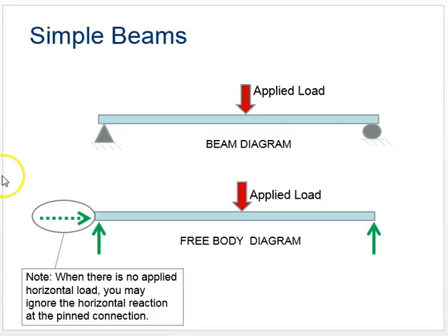This is going to be our first step when we do calculations. You'll see here's a fixed support. This is what I said, it looked like a triangle sometimes. And this is a roller support. Notice it's a circle. I said it could look like that. This is going to be our typical setup for the problems that we're going to do. And the first step in our calculations is to replace these supports with the reaction forces they go with.